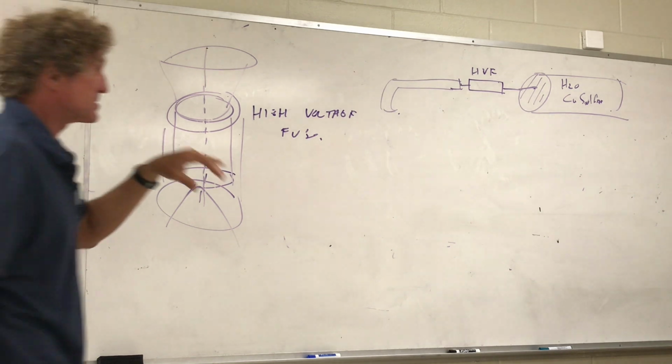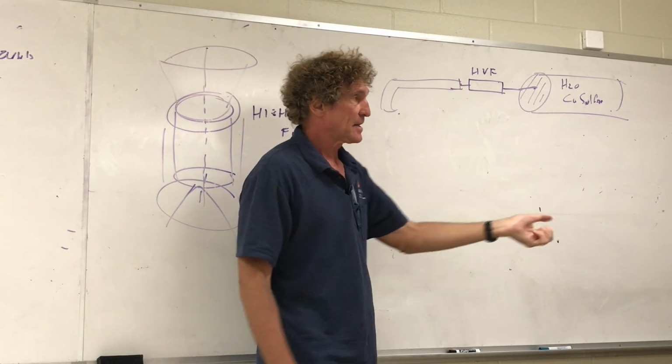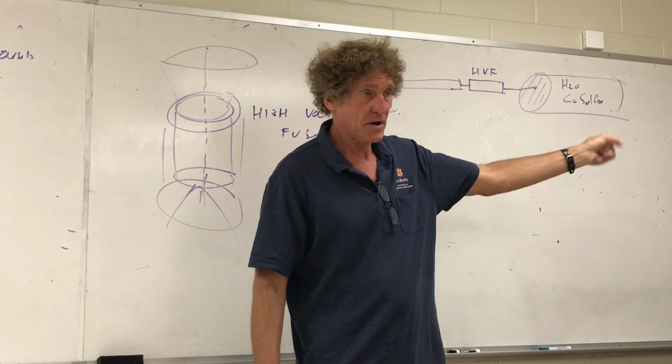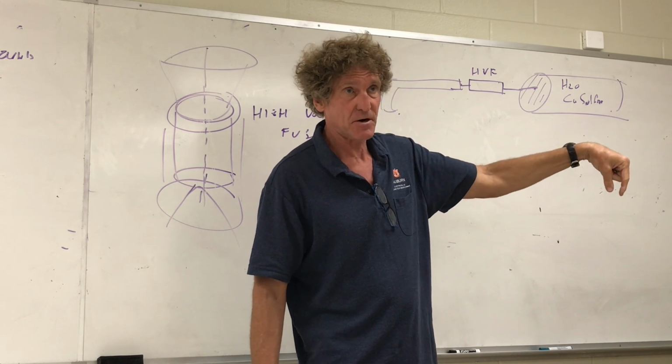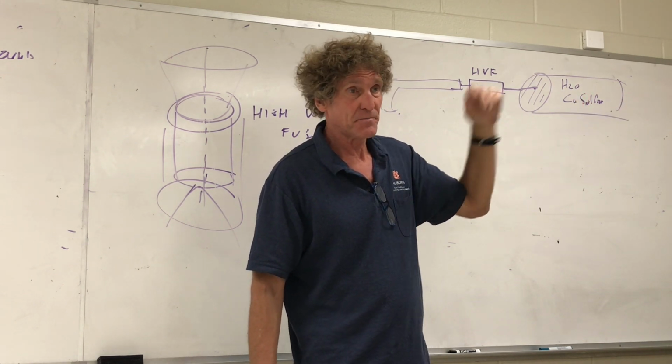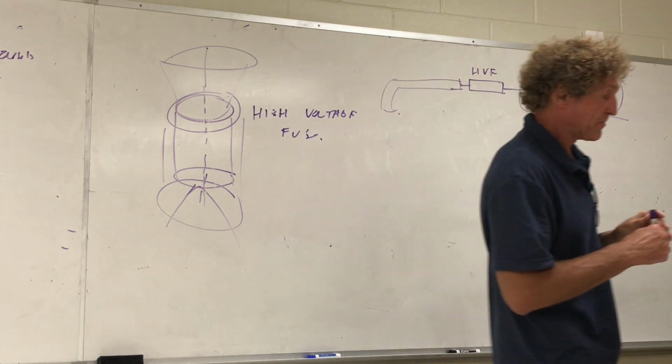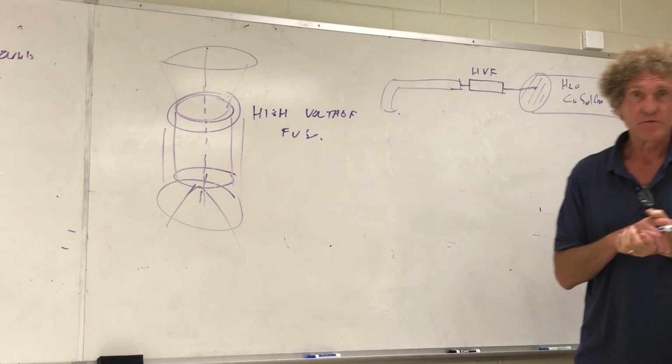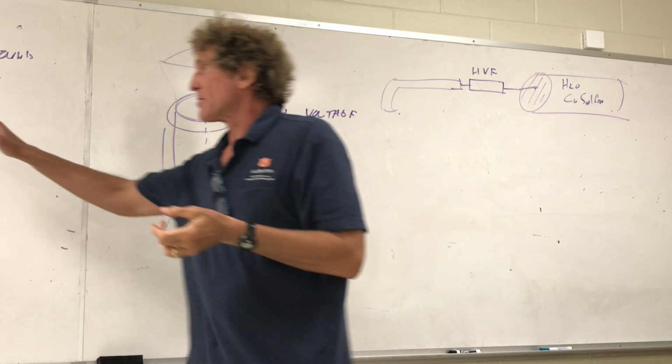Because when we discharge these things, there's an insulator here. You have to take it and put it on the capacitor, on the anode of each and make sure it was discharged. Because you can kill yourself with these things. You don't realize it until you're around it. That was my experience with high voltage fuses and stuff like this, and also the earth ground.